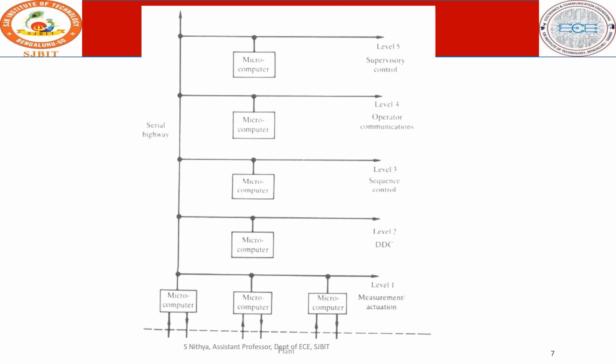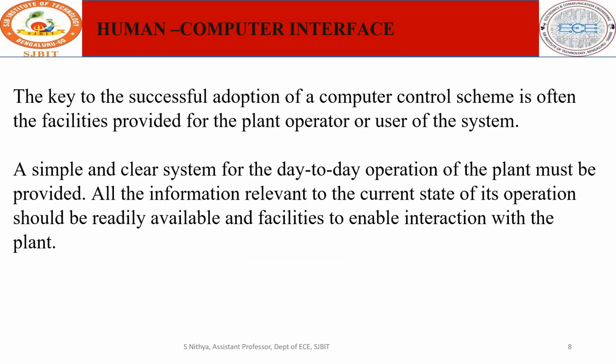It is not necessary to preserve these rigid boundaries; it may go beyond this also. So what are the major advantages of this system? The system's capabilities are greatly enhanced by the sharing of tasks between the processors. So the system is much more flexible than the use of a single processor. If any failure or disturbance or overloading occurs, only a small portion of the overall system will not be working. The remaining parts are working properly. So this is all about the hierarchical system.